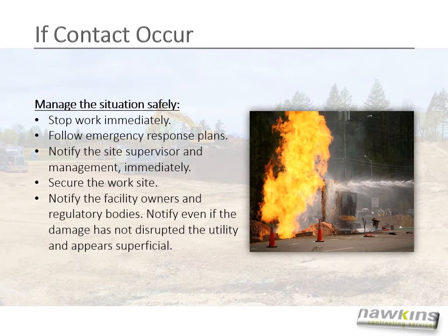If contact occurs, you need to manage the situation safely. Stop work immediately. Follow emergency response plans that are crafted in advance. Notify the site supervisor and management immediately. Secure the work site. Notify the facility owners and regulatory bodies. Notify them even if the damage has not disrupted the utility and appears superficial.